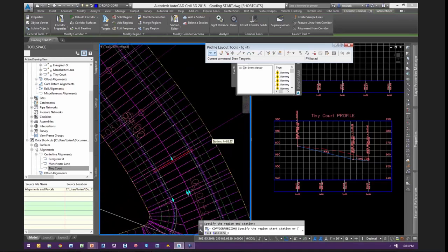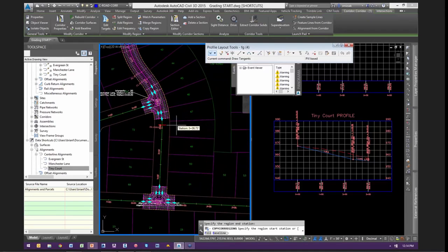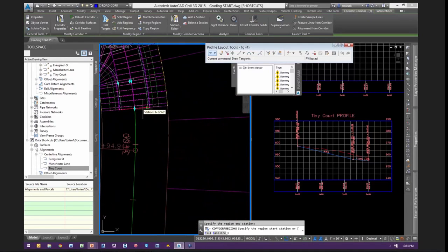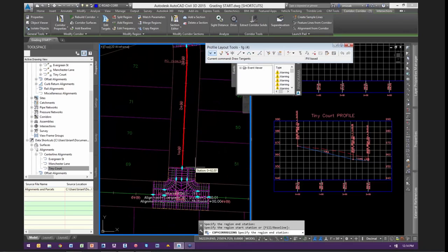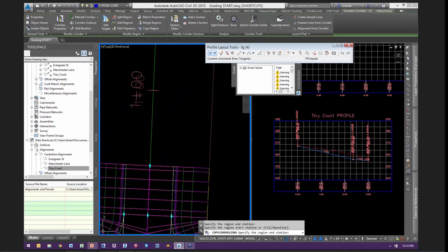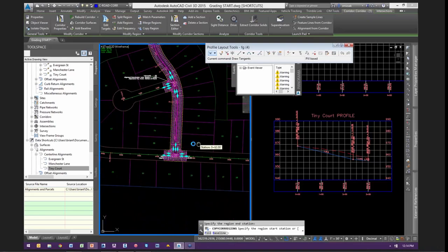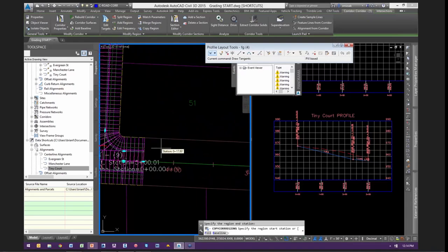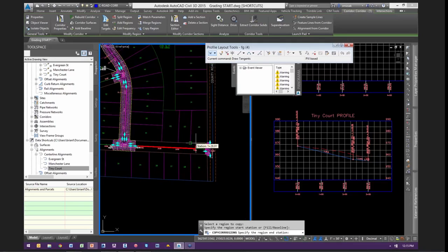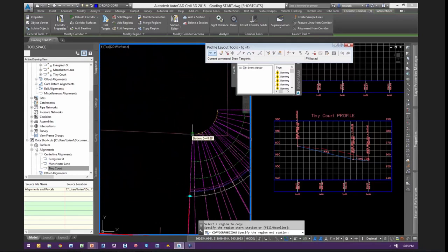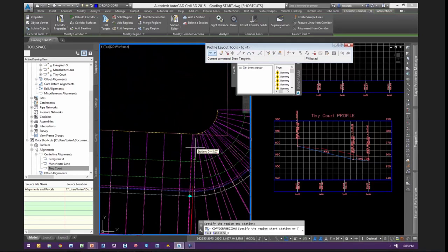to there. And I want to show you a nice little trick here. If we make a number of regions like this, all of these want to have the same frequency and target settings, which is to have no targets basically. That match parameters option for corridors, if you guys have never used that, it works pretty nice in this situation. So I'll show you that here.